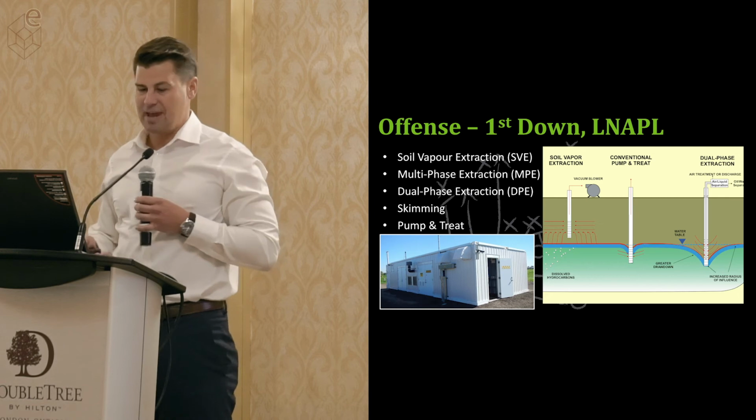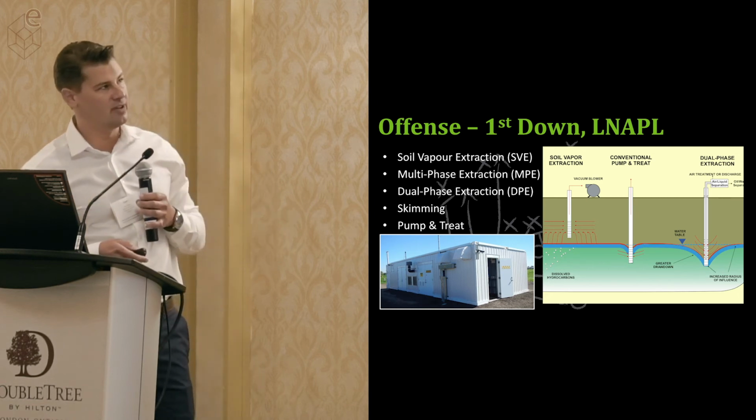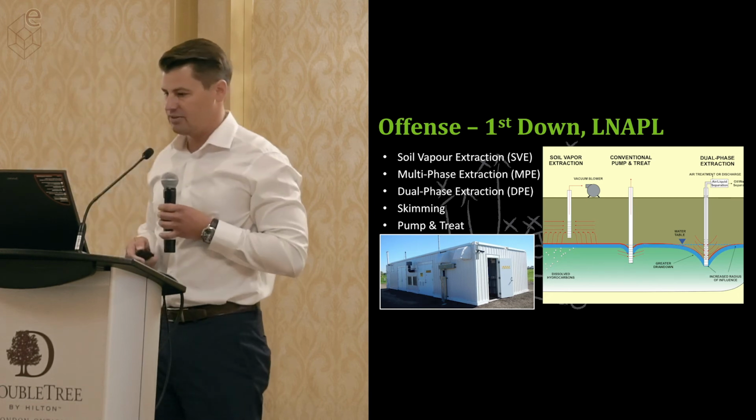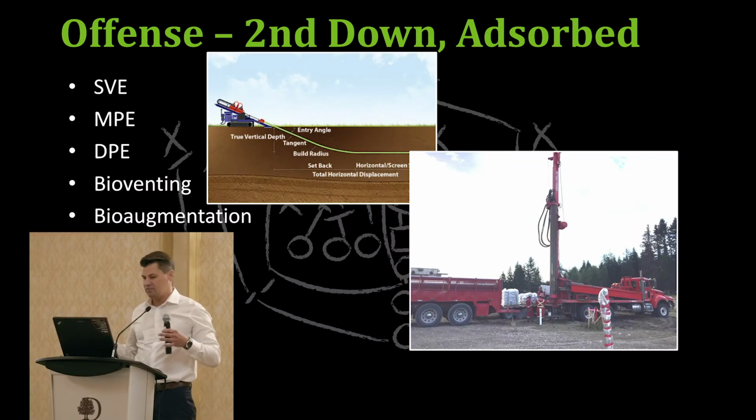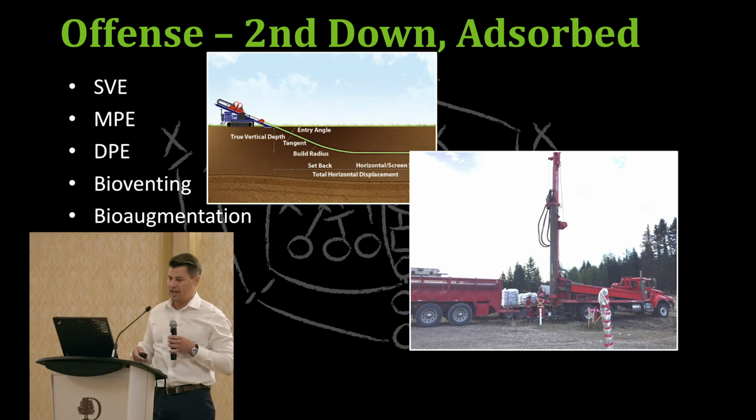Those are just a schematic on the right that shows the basic fundamentals of how those different technologies work. So presumably once you've got all the source, the free phase out, you still want to deal with what's adsorbed to the soil particles. Again, some of those extractive techniques like soil vapor extraction and multi-phase are also quite effective for doing that.